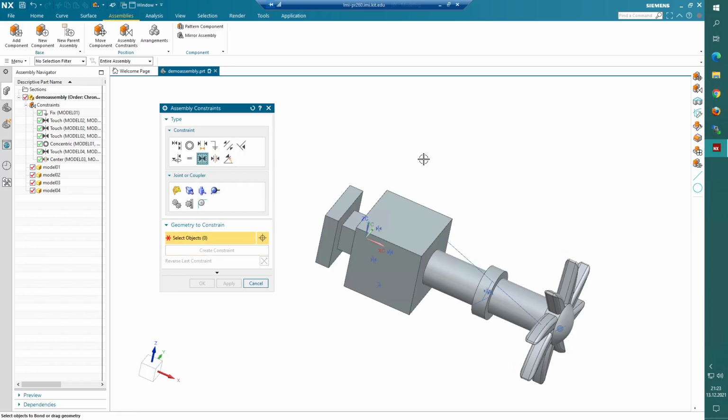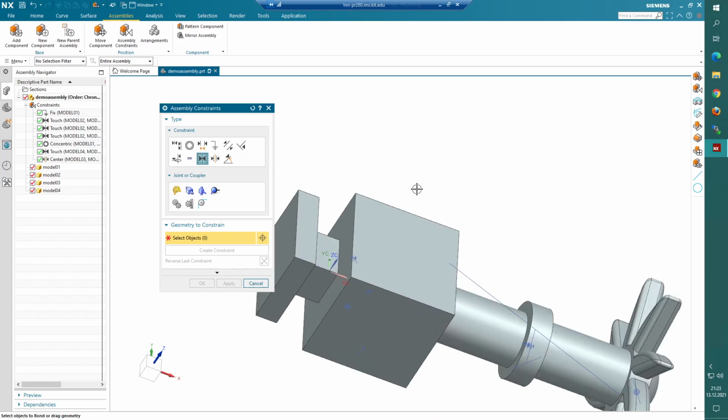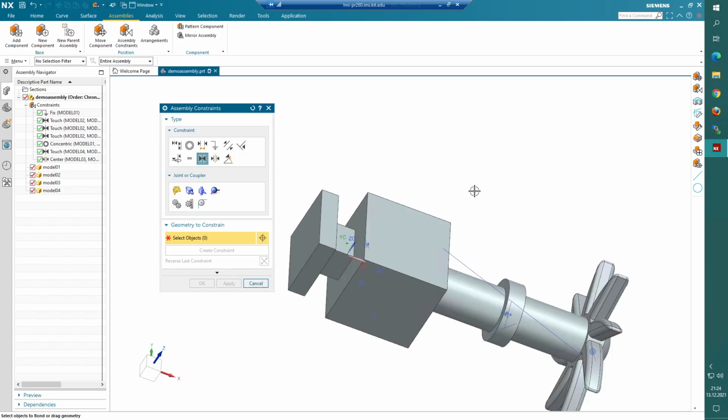Bond, that might be interesting. So here you just constrain two elements to be a rigid body together, so they can't be separated anymore, like we did with that one with multiple things. But here you could do it directly, but I think using that is not a very pretty way to do it. So usually the other constraints you can achieve bonding with a combination of other constraints in a better way. Fit, I have actually never used, so don't bother with that.